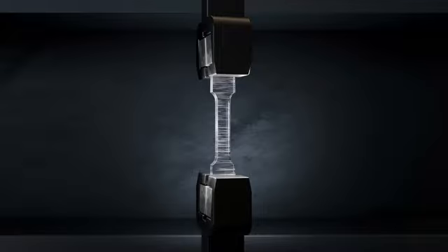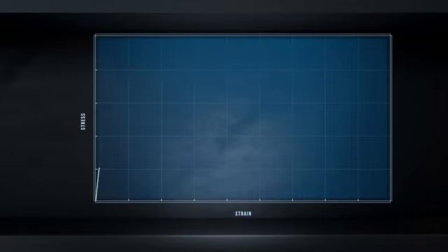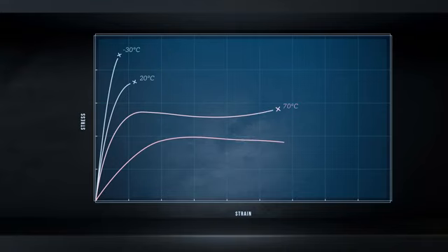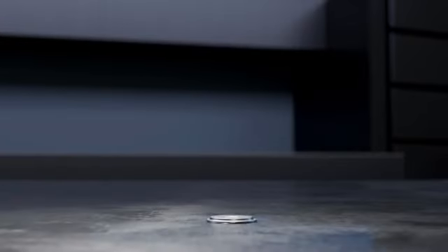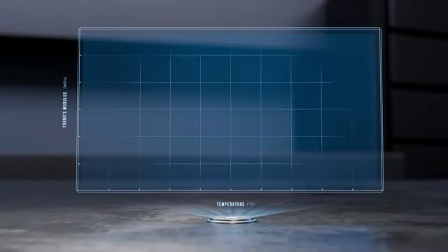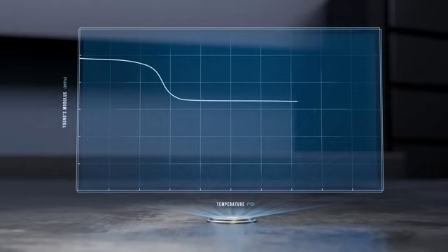Strength, stiffness, and other mechanical properties of polymers can vary a lot with temperature. Polymers tend to be relatively brittle at low temperatures, becoming much more compliant and ductile as temperature increases. Let's look in more detail at how Young's modulus changes with temperature for a typical semi-crystalline thermoplastic. At low temperatures, the material's stiffness is relatively high and stable, but as temperature increases above a certain threshold, it suddenly drops. Keep increasing temperature, and eventually the thermoplastic melts to a liquid, and the stiffness decreases to zero.